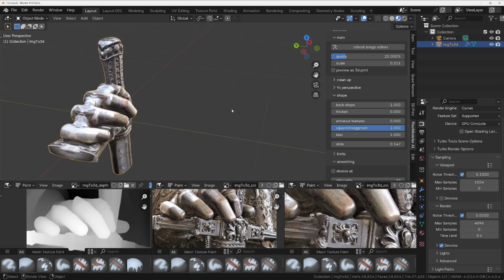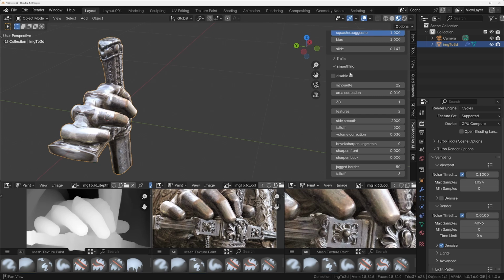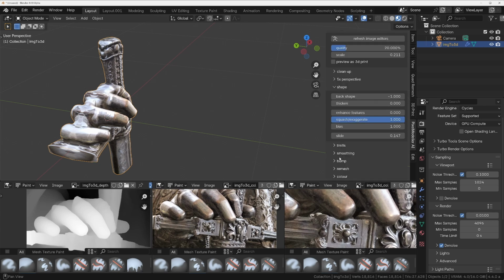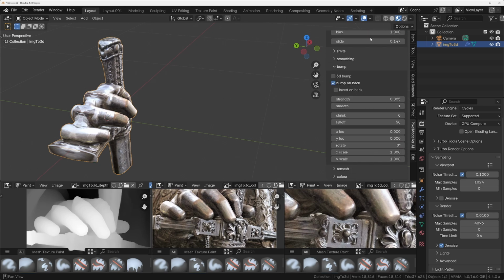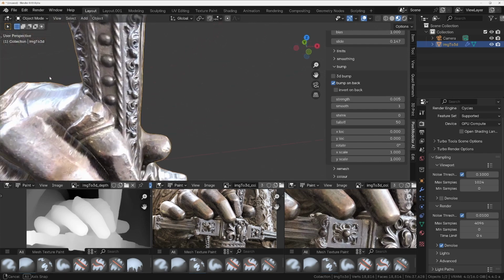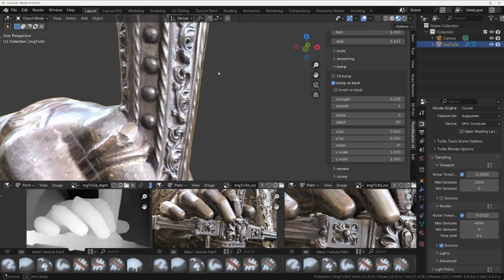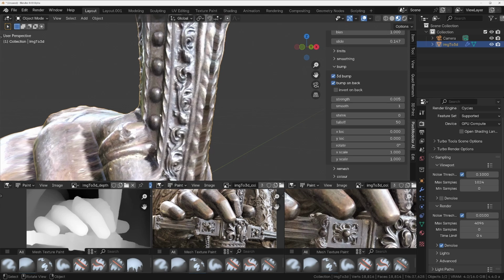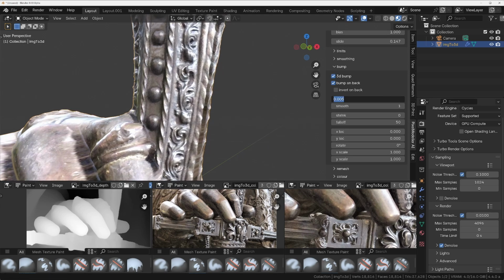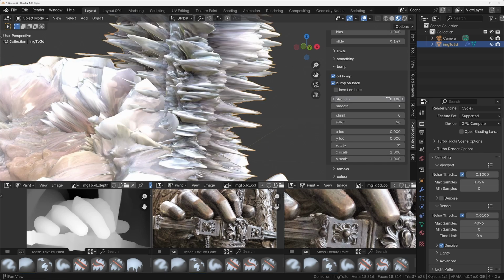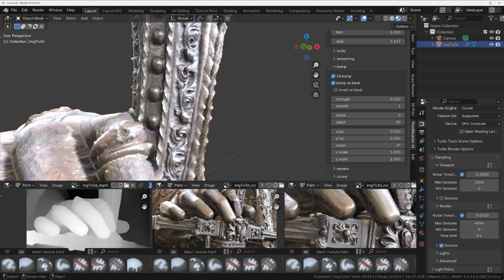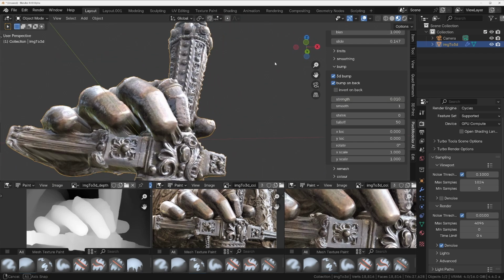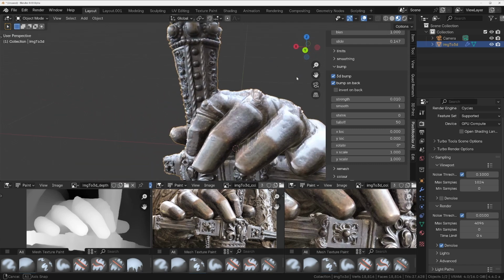And then finally, I'm going to turn on the 3D bump. So let's just come out of smoothing, down to the bump settings, and we'll change it to 3D bump. And what this is going to do is, on the sides here at the moment, we've not got any bump. So 3D bump's going to put it all around the actual object. And I'll turn this up a little bit as well, 0.1 perhaps. In fact, 0.01 rather. You see we've got the actual bump going further around the sides of the object.